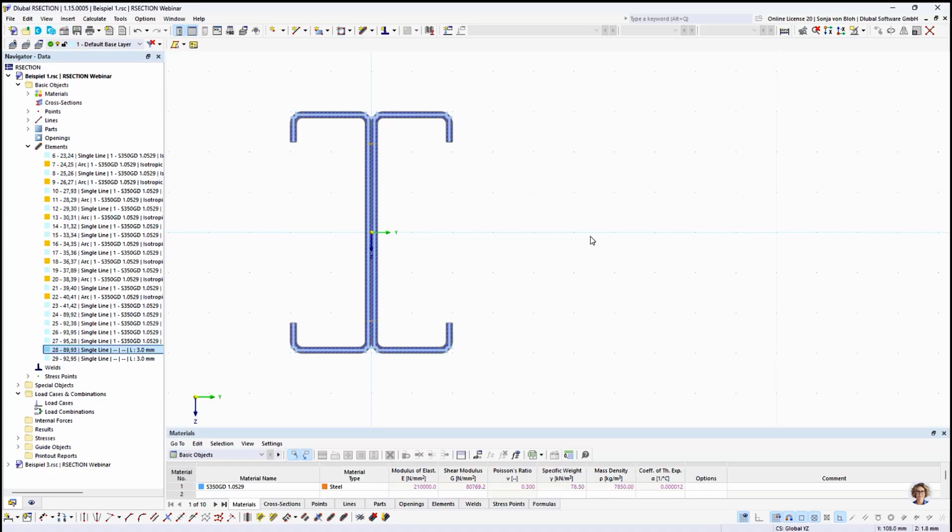At the same time, zero thickness elements are not considered as supports during the automatic generation of subpanels. As a result, a subpanel is not subdivided at the screw locations. This represents a conservative assumption. You can see here that this subpanel is not subdivided at the screw position here and here. In practice, however, it's often desirable to consider the screws as supports. This is now possible with the manual definition of subpanels.